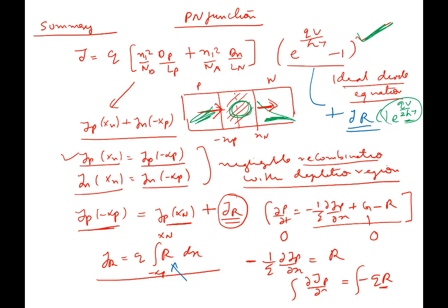And so if somebody were asking you, when does the first term dominate? Well, the first term dominates at medium or high voltages, while at lower voltages, this particular term will dominate here. And we've given you full expressions, and you can calculate the two components of current at different biases. Right? Now, the other complication in a PN junction is, before we come to this, if I were to plot ln J versus V, so note that this is there.